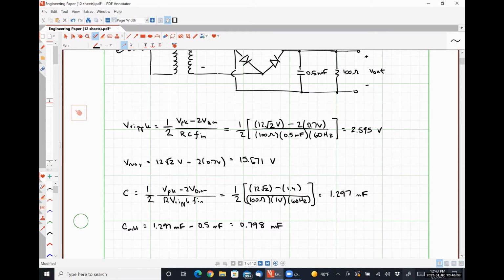Donald, you look slightly confused. So since you can't divide by zero, does that mean you're always going to have some ripple voltage? So you can never truly convert AC to DC? Yeah, you will always have some very, very small amount of ripple, right? Because the only way for you to not have some small amount of ripple is effectively this resistance to be infinitely large so that you just had an ideal capacitor.